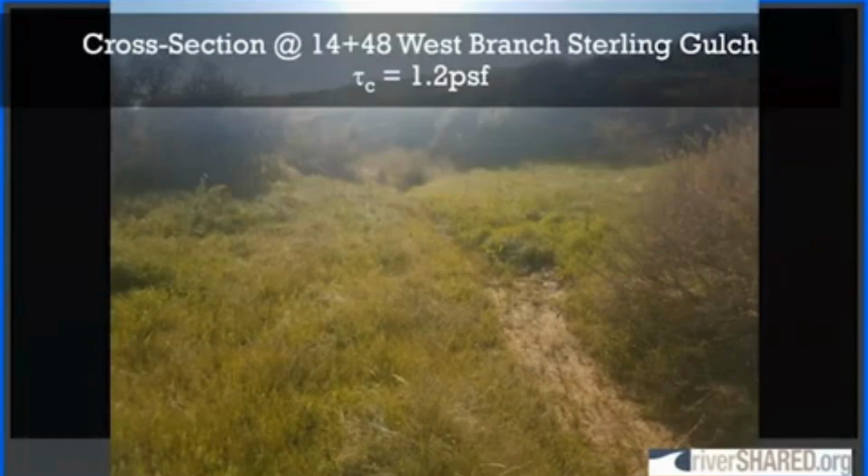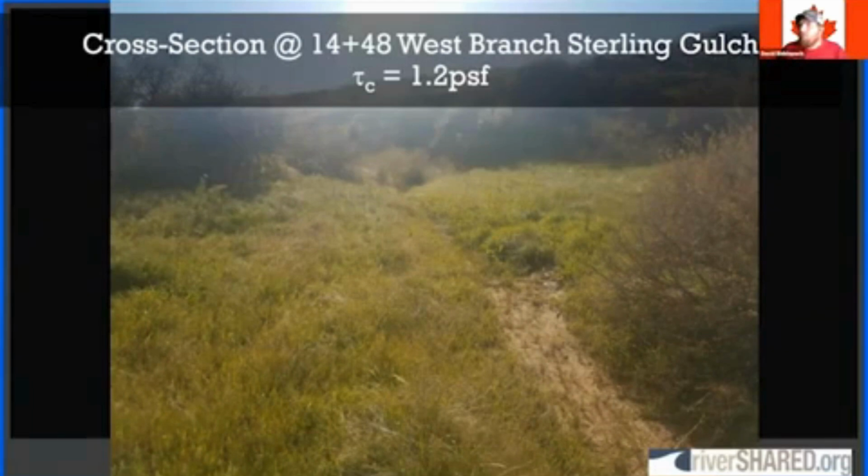So if we do this on enough sites in a regional location, then we can get a new reference for each parameter related to floodplain resistance coefficients. And we can say, hey, we think that there's going to be this vegetation that can establish in this location, and in this general region with the rainfall and with the vegetation potential, we think that you may be able to withstand 1.2 pounds per square foot. So then we can reconfigure floodplains and flood terraces for that distribution of shear forces.